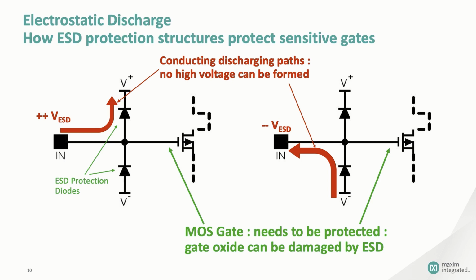Now, the last two requirements really don't have anything to do with ESD protection, but they do concern compromising device operation when there isn't any ESD event. You see, many inputs are expected to operate at high frequencies, maybe hundreds of megahertz, perhaps as high as a few gigahertz. That means a few picofarads of additional capacitance on the input can have a significant impact on the device parametrics. So for this reason, we have to keep the parasitic capacitance of the protection diodes as low as possible.